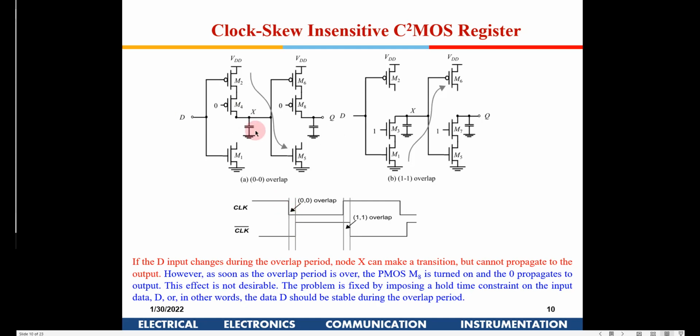Okay, so if you put a constraint of hold time, which is equal to the jitter, then during the positive edge of the clock, that issue of the new data being sampled can be avoided. For the new data, it means the register should always sample the previous data.